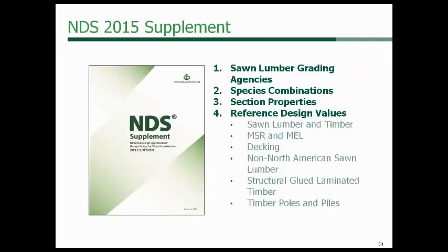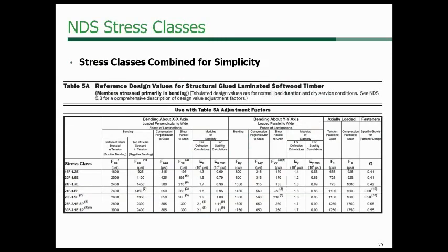As far as design values, Glulam is nice in that you can see that we have reference design values for it as part of our supplement. So Glulam, since it's a standardized product and not necessarily considered a proprietary product like other engineered wood products are, we are able to have stress classes that are available in Table 5A, which you can use to design with.